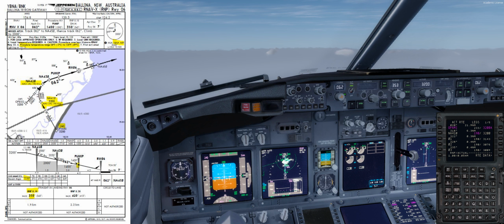So in this particular instance there are 2. There's an RNP 0.10 and an RNP 0.30. For demonstration purposes and in light of the weather here today, we'll be using runway 06 with an RNP of 0.10. ICAO certainly encourages pilots to use the largest possible RNP to reduce the possibility of inadvertent cross-track alerts on approach. If the weather conditions require the use of the minima from a lower RNP, then it would need to be manually entered at the briefing stage. As we know, 0.3 is the default.